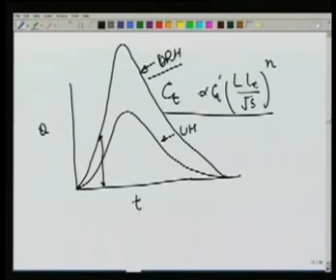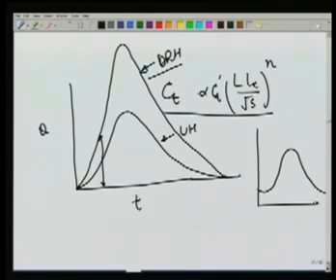And once we get the DRH, we can add the base flow and get the total runoff hydrograph, which would look like this. Our aim of developing this total runoff hydrograph is to be able to answer questions like what is the maximum flow in the stream, what is the minimum flow in the stream, what will be the total amount of water which passes the stream for a fixed period of time, or there could be a lot of other questions.